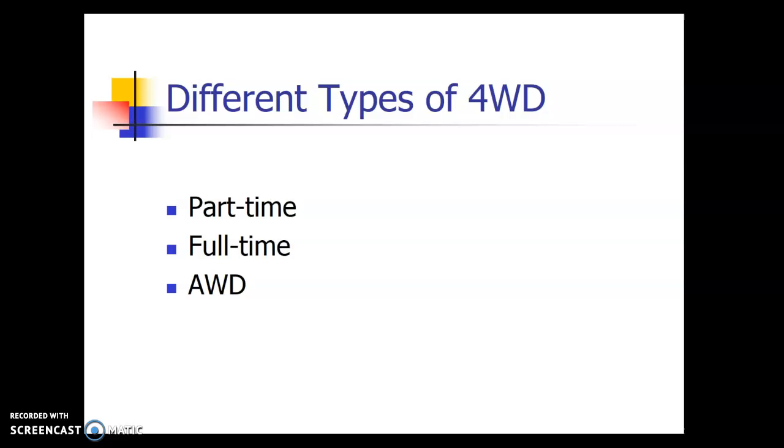Part-time four-wheel drive, think of your old-school military Jeep, right? You get the locking transfer case knob inside the car, locking hubs outside. You put it in four-wheel drive when it's gnarly out, and you feel awesome, right? You get out, you lock it in four-wheel drive, you lock in the hubs, and you get to climb out of whatever dilemma you're in, out in the woods or wherever you're at. And when you get back to the road, you have to put it back into two-wheel drive.